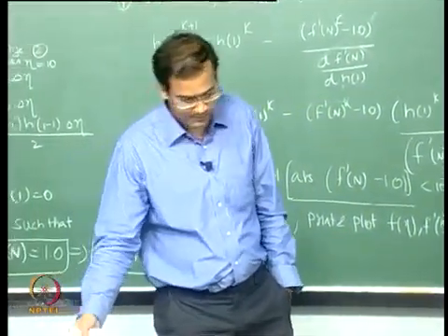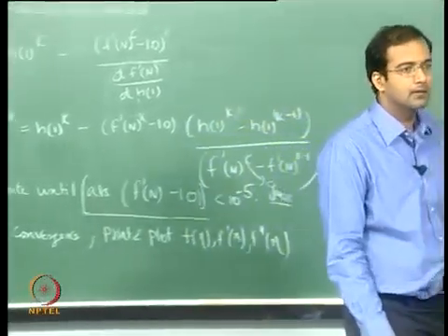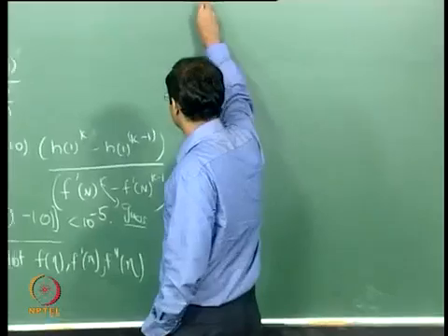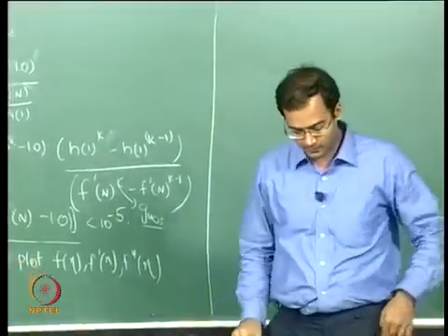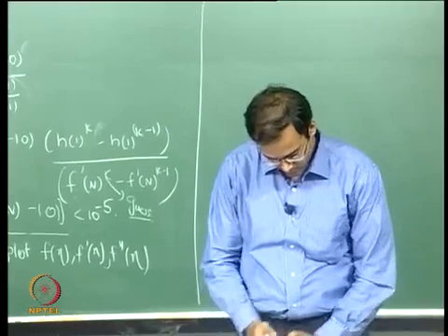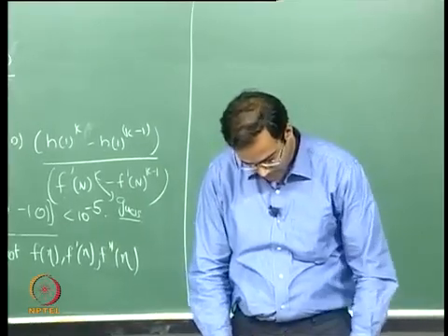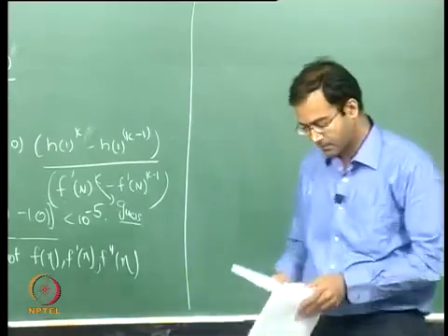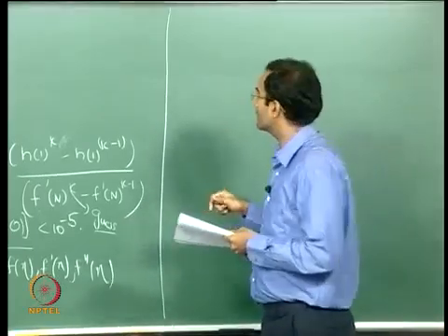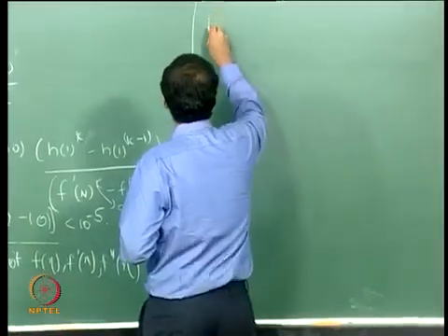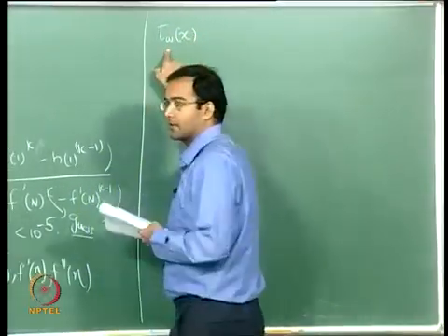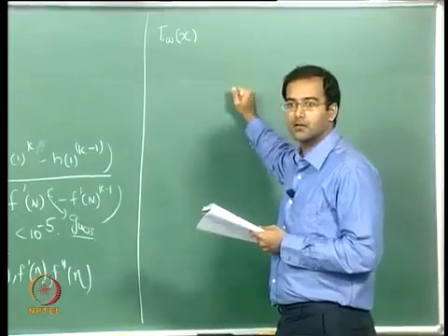Okay, so assuming that now you have the solutions to f as a function of eta, we will now calculate the other derived quantities. The first quantity that we are interested in, since we are doing this for a flat plate, is the local shear stress, that is tau wall as a function of x. So the shear stress at the wall varying locally.